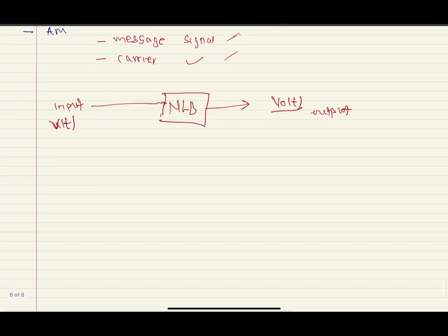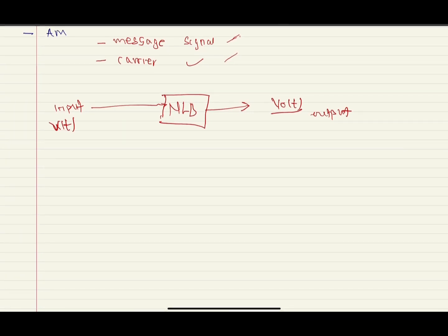After you have passed it through the nonlinear device, as I was telling you earlier in my previous video, because of the nonlinear nature of these devices, the output most of the time includes some harmonics, which are integral multiples of the fundamental frequency. This happens because of the nonlinear nature of the device, in this case our modulator. Bringing that to what we are doing right now, we assume that our message signal and the carrier that we are using for our transmission are our fundamental frequency.